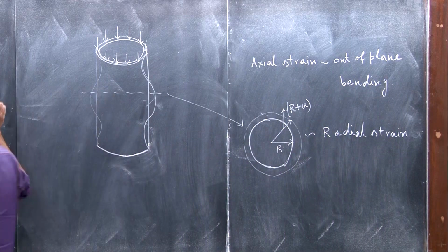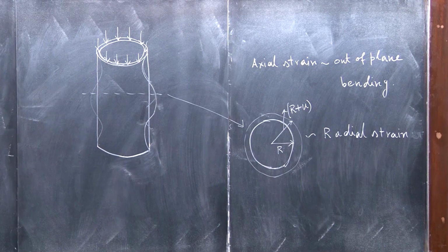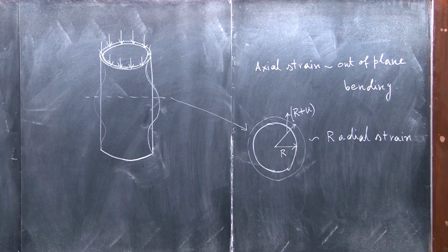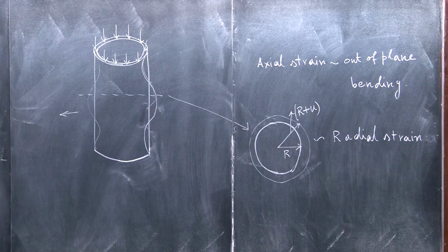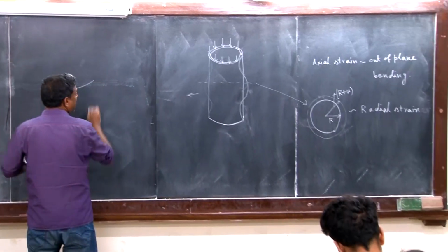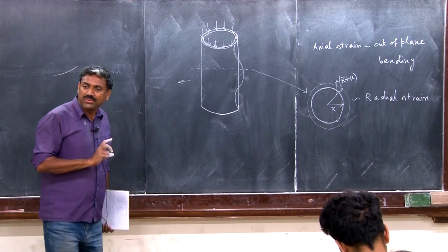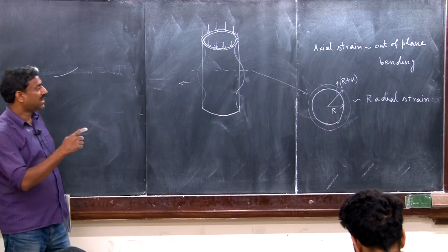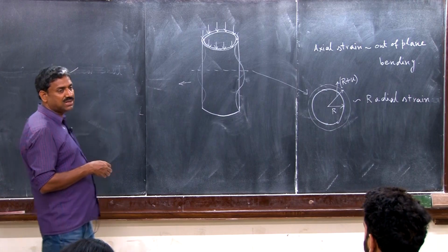When considering axisymmetric buckling of a cylindrical shell, we take a simple strip. Please note that a cylindrical shell is characterized by a single curvature, the curvature along the circumference. In the other direction there is no curvature; it is infinite radius of curvature.